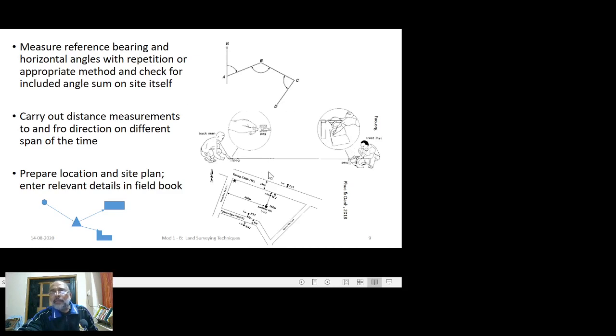Once the surveying operation is completed, that is measuring of the angle, measuring of the distances, measurement of the bearings, one should draw some rough sketch which is depicting the piece of the land on which we have worked. Such a sketch that is drawn on the site in relation with some dominant feature or naturally existing magnetic north is called as site plan.